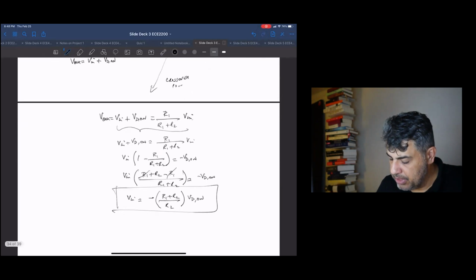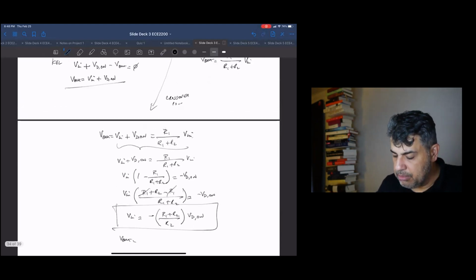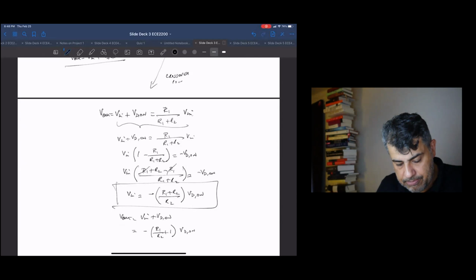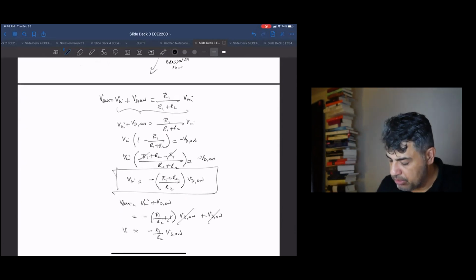Okay, and then V out is V in plus Vd on, right? So it'll be minus R1 over R2 plus 1 Vd on plus Vd on. So these two, basically this guy and this one, so you end up with minus R1 over R2 Vd on for V out.